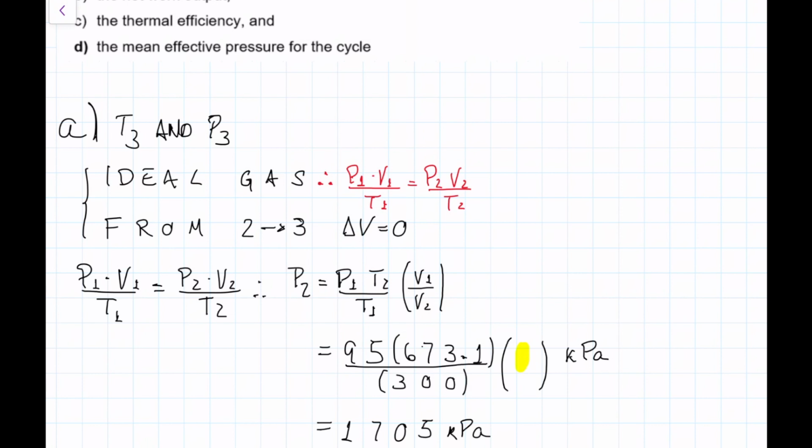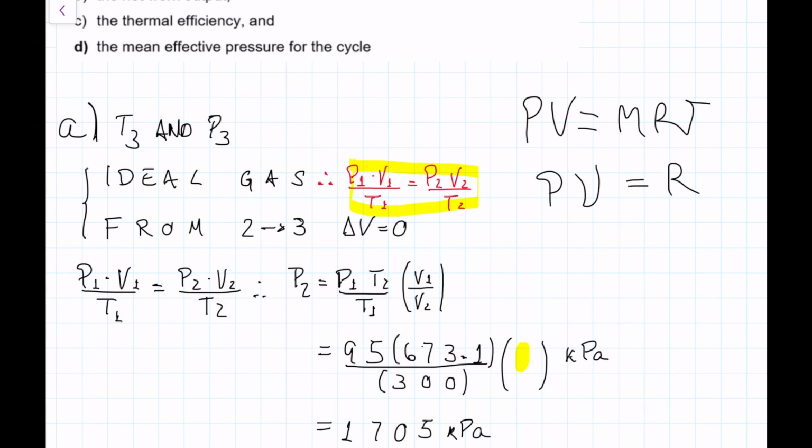So if it's an ideal gas, it respects the relationship PV equals nRT, and we can use that relationship as P V1 over T1 equals P V2 over T2, right? So we're doing PV equals mRT, and then we're doing P specific V equals RT, because volume over mass is specific volume, so therefore P specific V over T equals a constant.